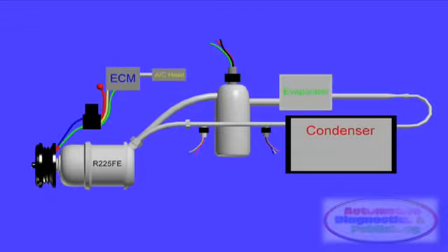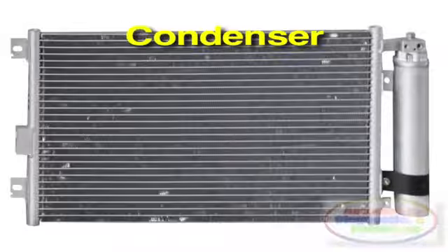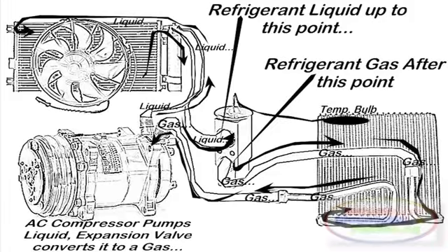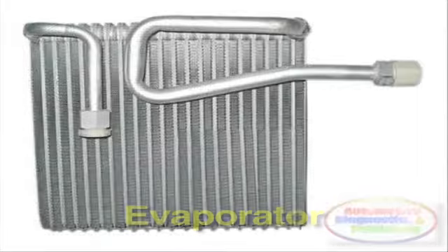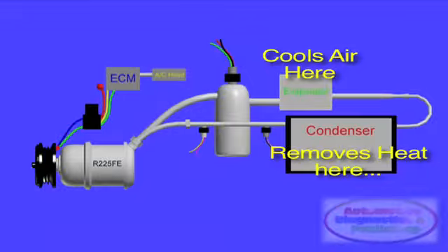The basic principle of an air conditioner is that a refrigerant liquid is pressurized, passed through a condenser to be cooled down, then through the receiver dryer or accumulator, through the vaporizing device like the orifice tube or expansion valve, then turns into a cold gas, which flows through the evaporator and back to the compressor. At the same time, an air blower pushes air through the evaporator, which is then cooled by the cold evaporator radiator-like fins. There's always some thermal loss, but the system works fairly well. It works like a pump exchanger, by removing heat from refrigerant liquid.